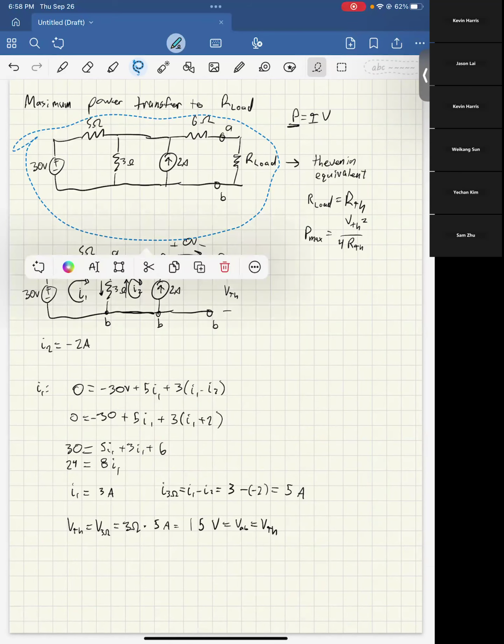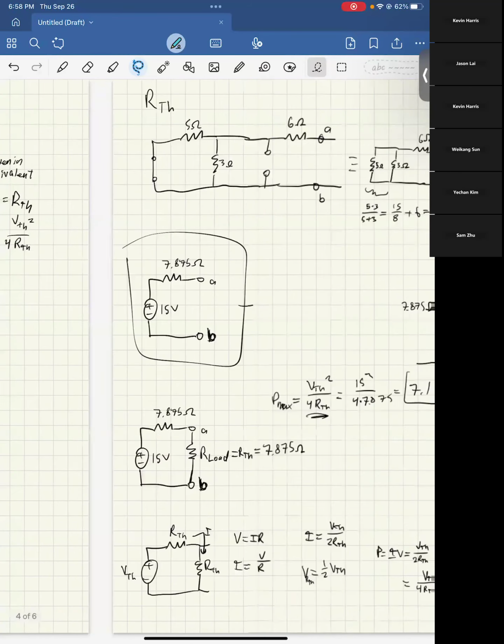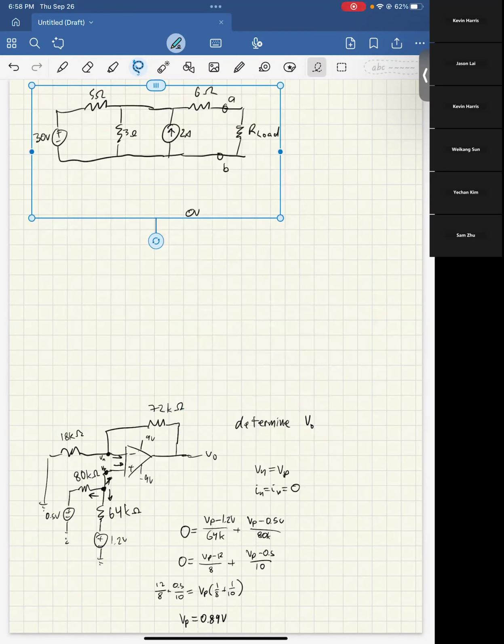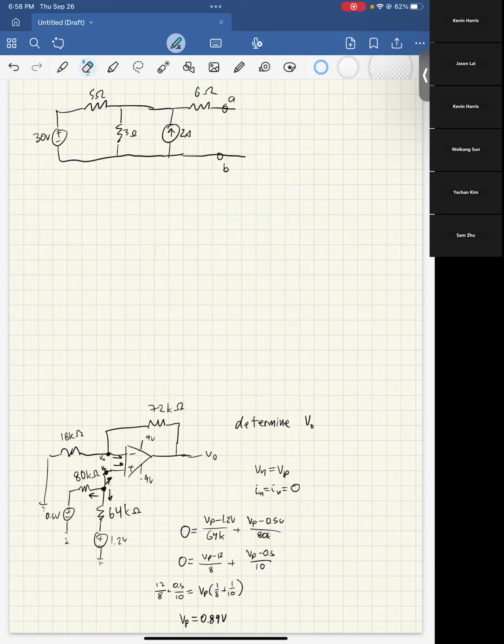sorry to get sidetracked, but I just want to make sure I'm getting to the questions that I see. So the other method is, instead of having this load resistor here, you would replace it with a short circuit, and then you want to find this ISC. So here, I'll do an I1, I2, I3, and you do this mesh current.